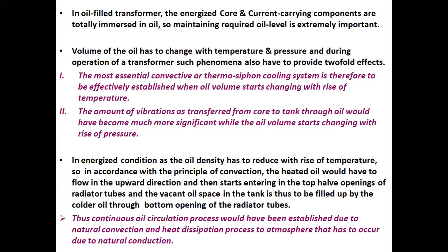In energized condition, as the oil density reduces with rise of temperature, in accordance with the principle of convection, the heated oil would flow in the upward direction and then start entering the top valve, top half opening of radiator tubes, and the vacant oil space in the tank is thus filled up by the colder oil through the bottom opening of the radiator tubes.